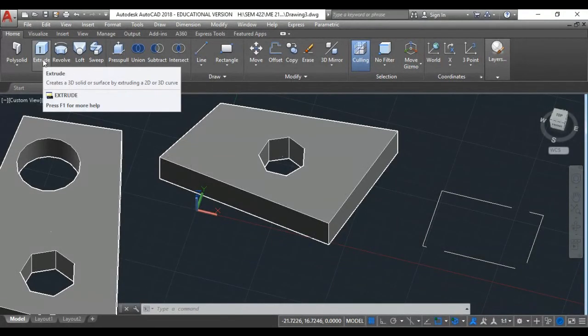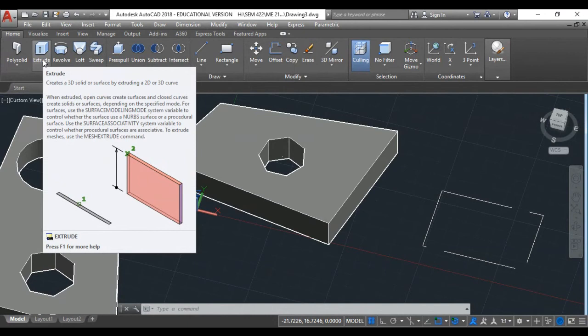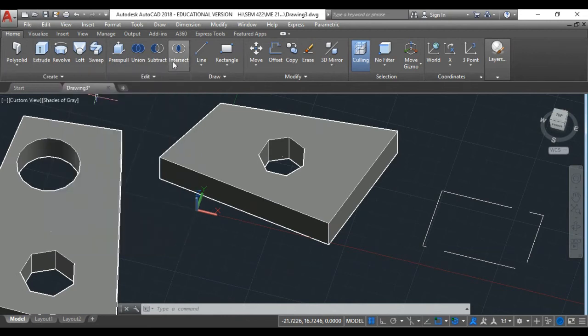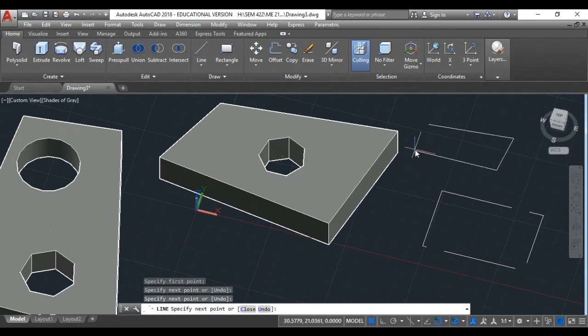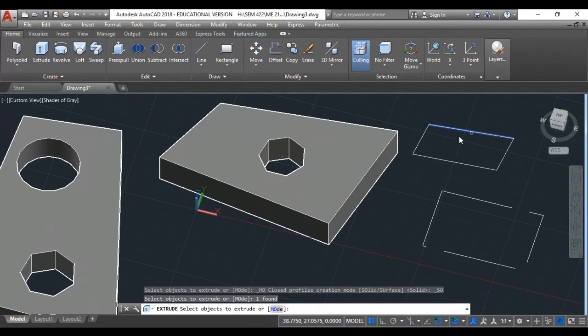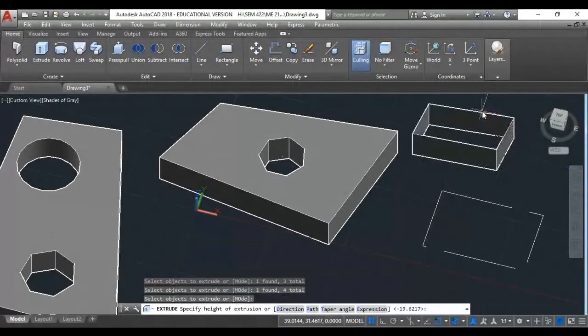Usually, when you draw that rectangle line by line, as 4 separate lines, we're not able to make a solid model. Remember? Let me draw the same rectangle again, or something similar, but drawing it line by line. Do you remember guys when I used extrude I was not able to choose the area in between, and I was able only to select the edges, and after selecting the edges whatever will be created will be an empty box, not something solid.